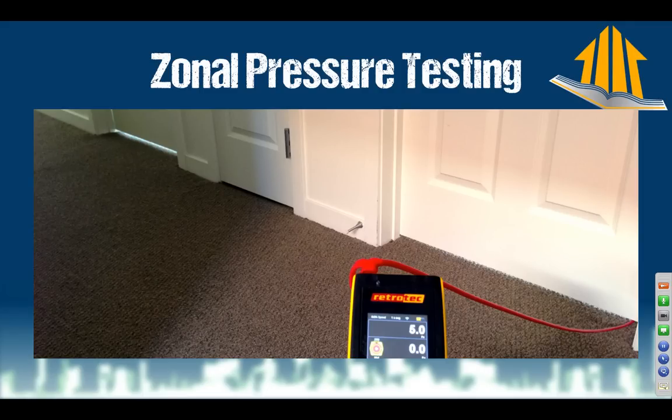And if you have a home and you're looking around right now, go ahead and count how many supply and return registers you have in the room that you're in. And if you only see supply registers, that means that when you close that door, it's going to be pressurized. If that number on my manometer is over 3, that's a problem. This is the kind of thing that you can really start to test.